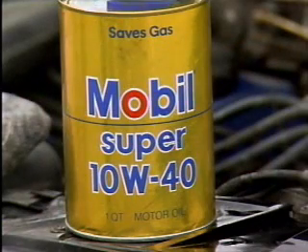In low temperature applications, lower viscosity oils are usually more suitable. They flow more easily at low temperatures and can reach moving parts better than thicker, high viscosity oils. In high temperatures, a thicker, high viscosity oil is usually needed. The oil has to be thick enough, that is, have a high enough viscosity to maintain a film over the moving parts it must protect. Many oils, of course, have to be able to lubricate in both low and high temperatures.